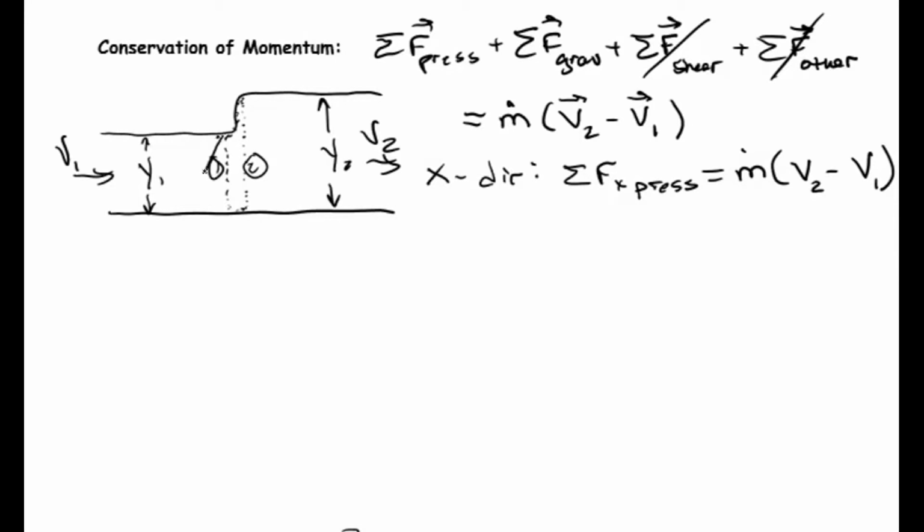So if that's the case, then we can write our pressure just like we did in statics. So it's going to start at 0 gauge at the top, and it is just going to increase due to depth. And if you remember, whenever you drew the pressure forces, they always had to go from outside your control volume into your control volume, and that's going to help us get our signs right.